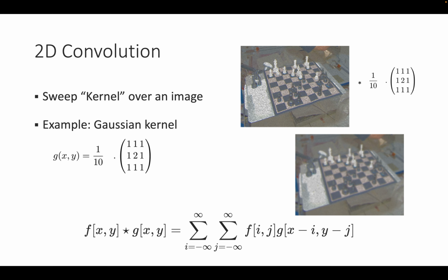And in order to grow those, we can change the kernel size. We can use a 4 by 4 kernel or a 5 by 5 kernel, or we can use a 10 by 30 kernel in order to grow objects vertically more than to the right. And then once we turn the robot, we can use a 30 by 10 kernel, but we can also have kernels where the robot is kind of diagonally in it, and we have zeros and ones where the robot is.